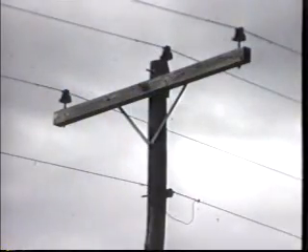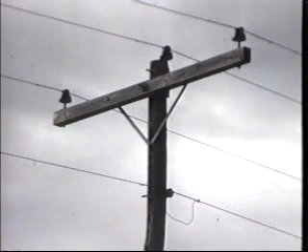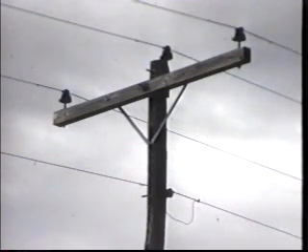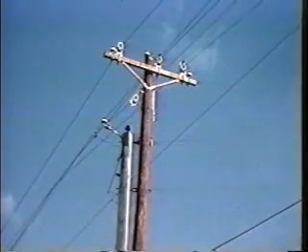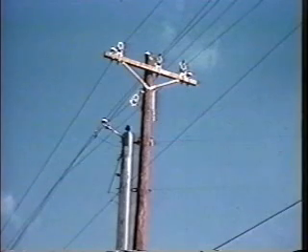When moving from single-phase to multiple-phase, most commonly three-phase lines, a very similar construction is used to those which have just been reviewed. The significant difference between three-phase and single-phase is the spacing required between individual conductors. Crossarms are used to achieve horizontal spacing. Again, we will use conductor angles to differentiate the various types of structures commonly used.